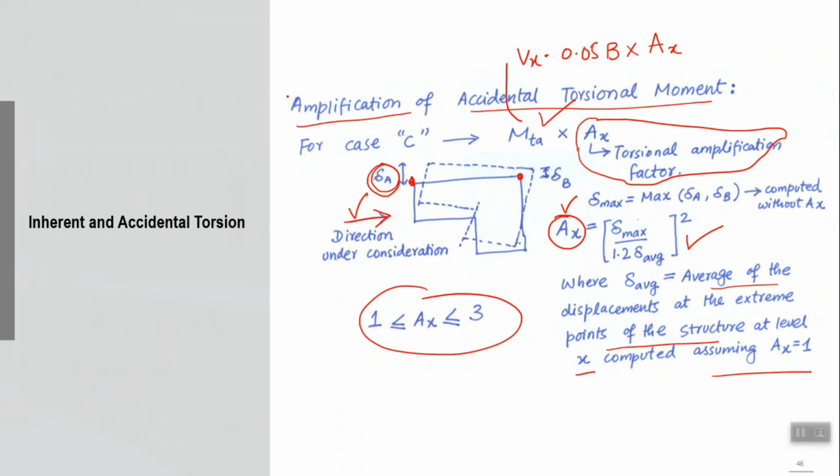I should have mentioned that exact provision here, but if I remember correctly, if you have type 1A or 1B irregularity and at the same time a seismic design category D, E or above, then you calculate Ax and repeat your analysis including Ax.